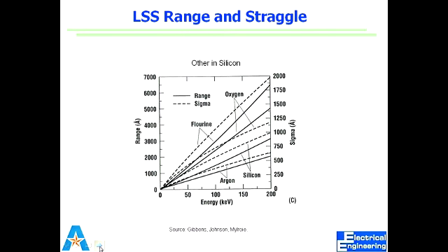And it basically isolates the top from the bottom, right? So if you're making devices just on the front, now you can make devices on both sides. This is what we call SOI technology. That's what they use in industry. They use silicon on insulator. So it can give us what we call silicon on insulator wafers.